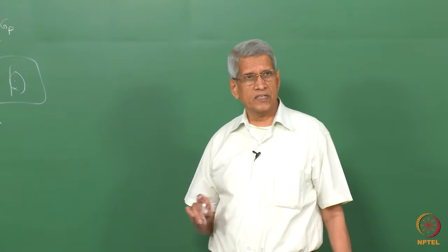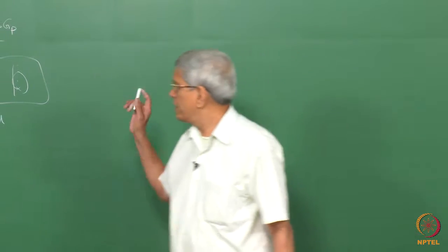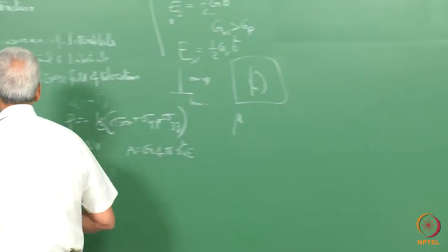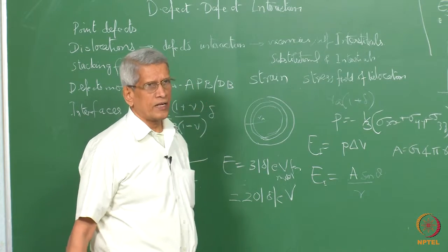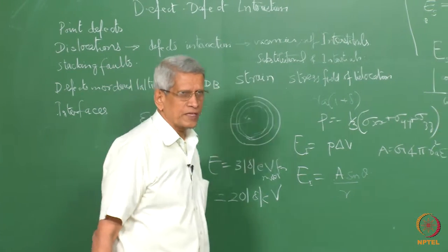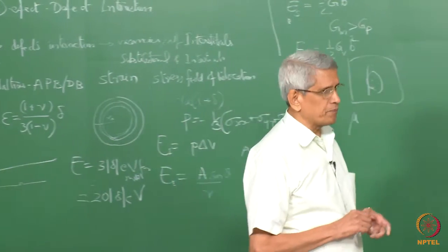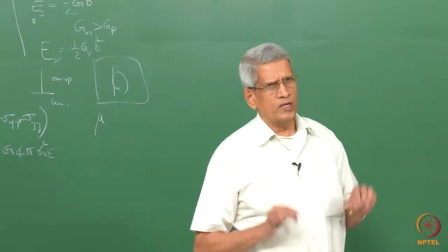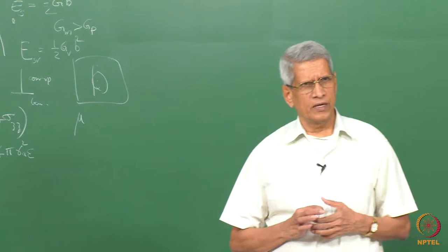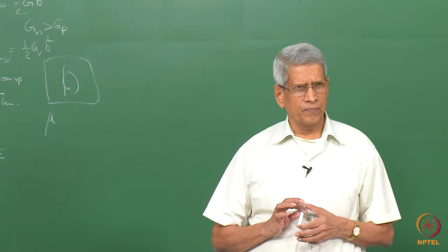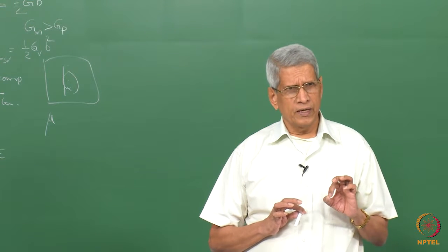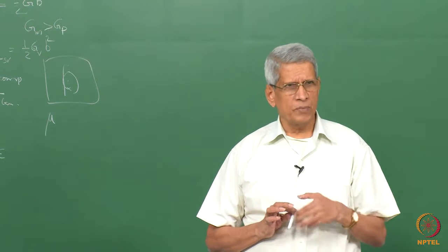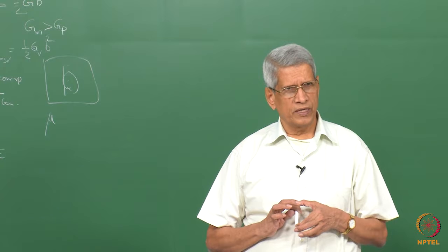This sort of interaction, what is the consequence of it? Here we have considered vacancies. Now let us take the case of substitutional or interstitial solutes also. Suppose a substitutional defect or an interstitial defect is present. This defect can have a positive misfit or a negative misfit.